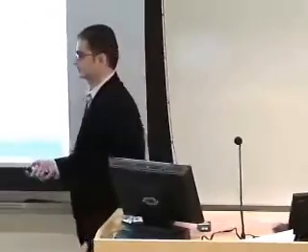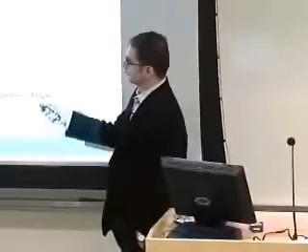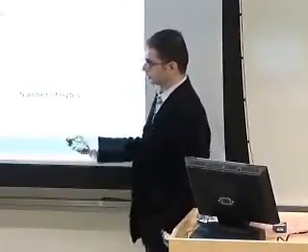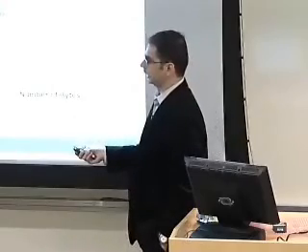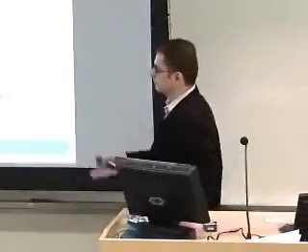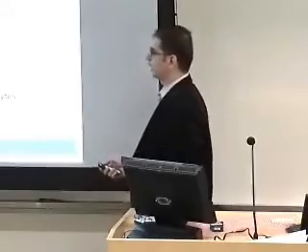So what you can actually see here is the evaluation we did on the actual mPlatform in terms of the end-to-end delay. Now, comparing with I2C, we're actually better, but this is not a significant measure of how well we did, because I2C is highly inefficient, we know that. The nice thing is that depending on the communicating pair of processors, we can automatically adjust the end-to-end delay. The faster the processors we're using, the faster the actual end-to-end delay will be. With respect to I2C, when ARM7 processors are used, we might go down by 90%, and when MSP430 processors are used, we might go down by 40%.